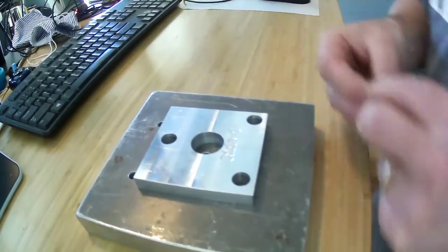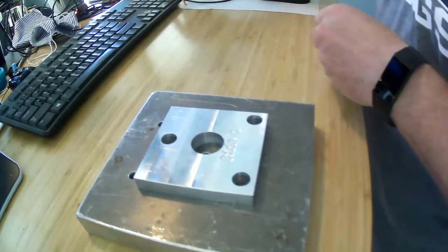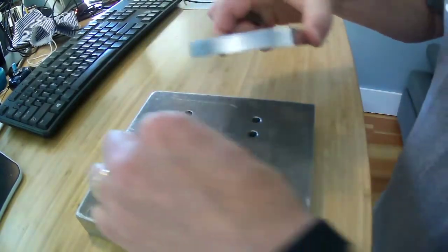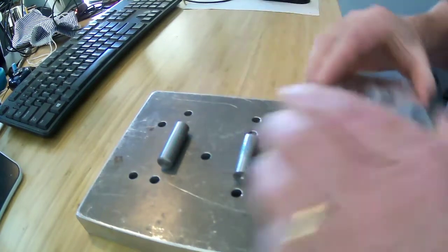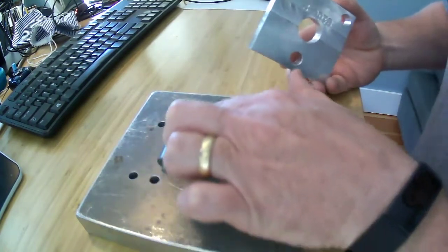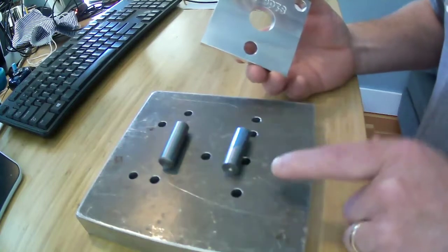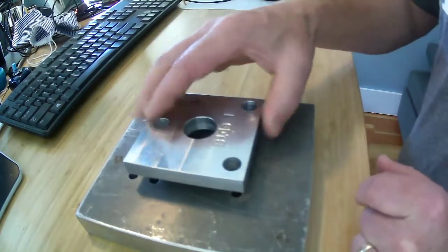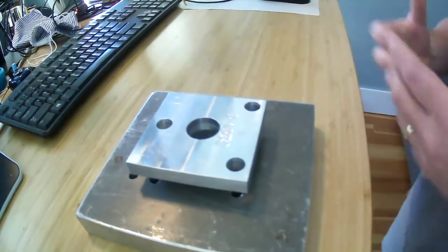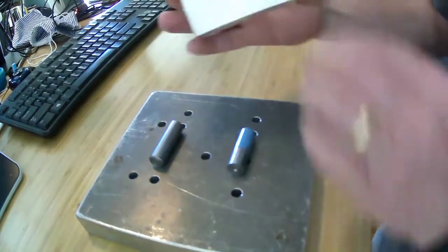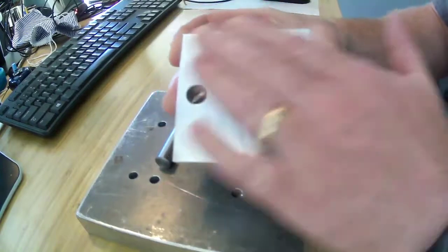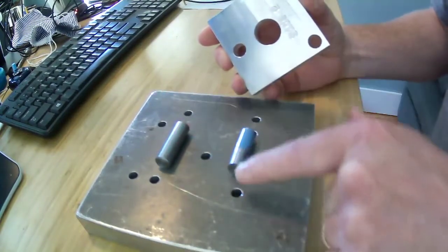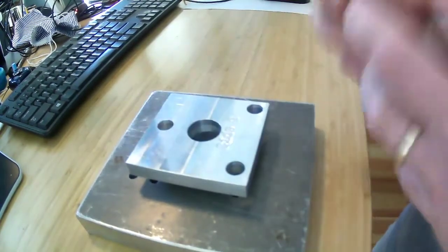Okay, how can I make this better? Well, one thing I could do is use 2 cylinders, because now I've taken the contact and put it along a line on that cylinder and along a line on this cylinder. Okay, so that's way better, right? It used to be that the contact was happening somewhere along this entire surface, and now I've reduced it to these 2 lines. So I have increased my determinism.